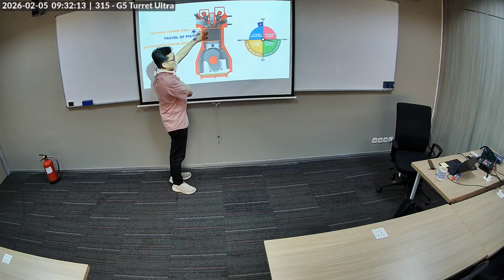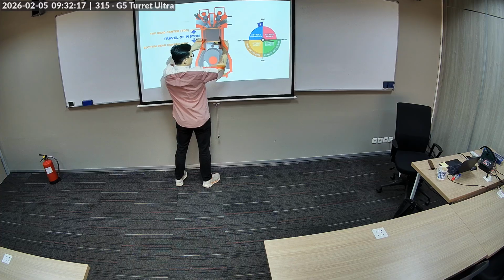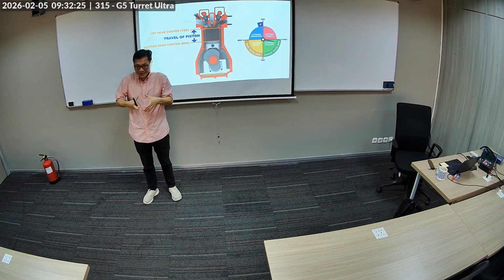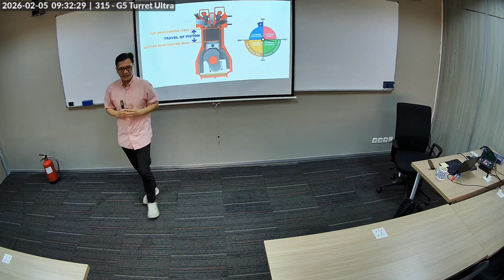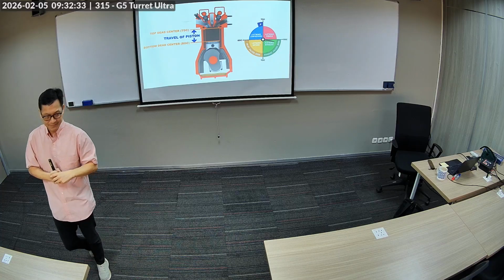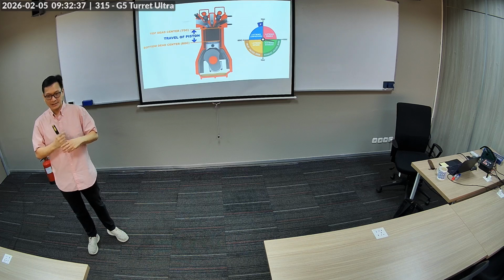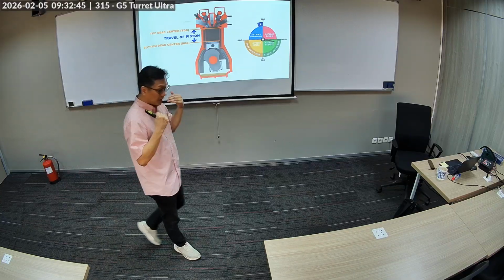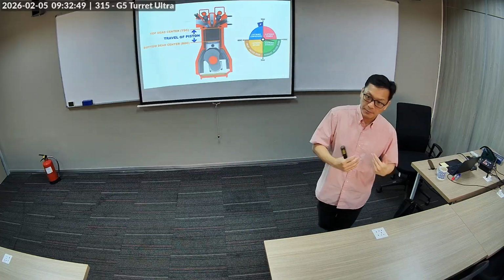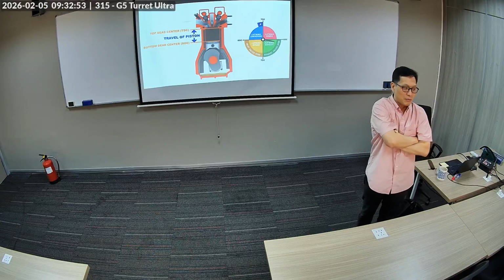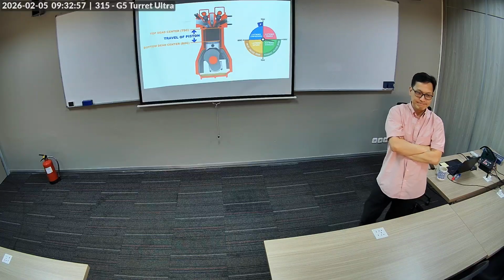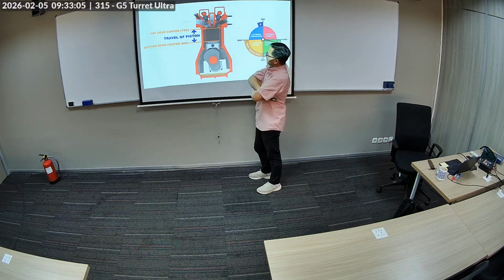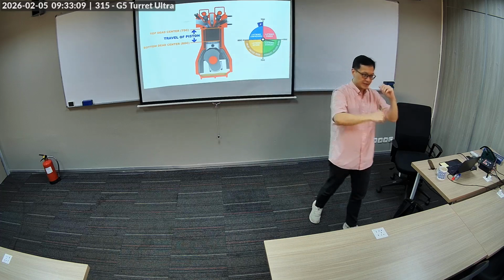Engines that are designed to do high RPM are usually shorter stroke, bigger bore. So kind of a bigger diameter, but shorter stroke. Can anybody guess why? Why would that give us a higher limit in RPM? Let's think, travel distance. Less travel distance means, think about limits. Think about the limit of red line, the high RPM limit. What would limit the maximum RPM of your engine? The weight of the piston and oil. Sure, the weight. But connect that to the geometry of the combustion chamber.